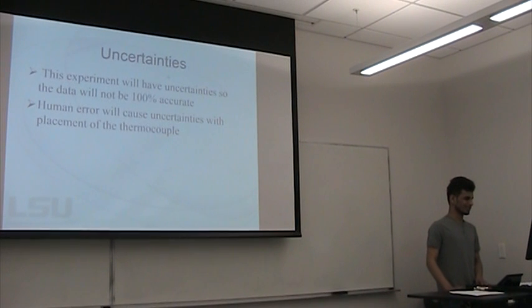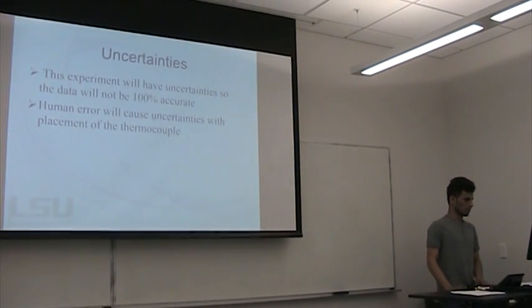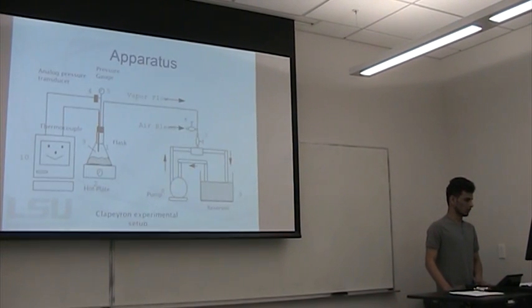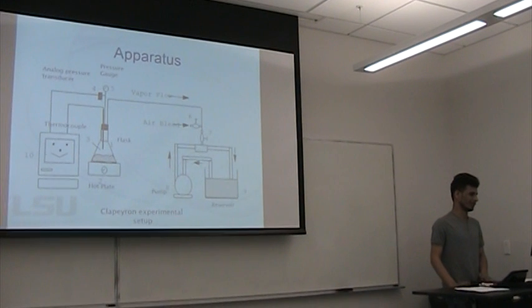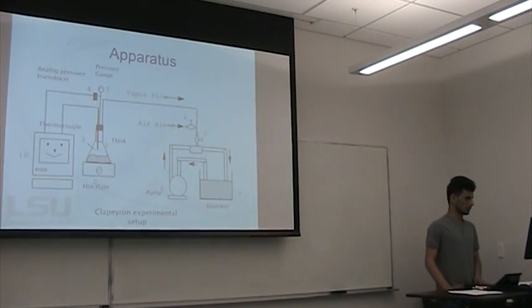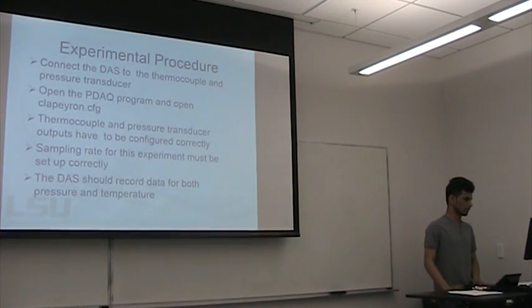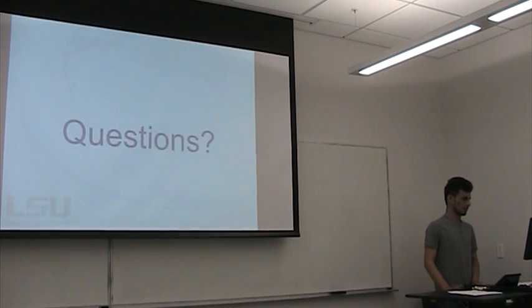We should have uncertainty in this experiment. Well, it depends on how we submerge the thermocouple. If we submerge it more than 0.75 inches, we might not get accurate data, so we have to make sure it's 0.75 inches into the water. That's it. Any questions?